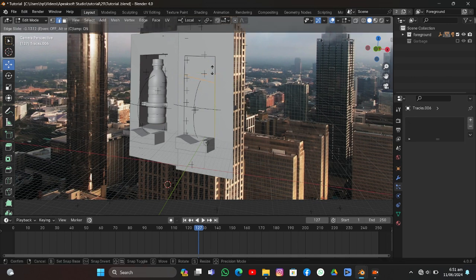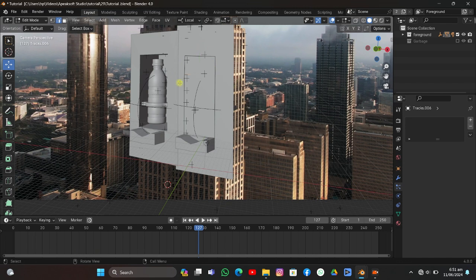I might not explain every single thing because I really don't remember what I left. I'm gonna hit K and I'm gonna make these loop cuts. I'm gonna hit Control B to add enough loop cuts by scrolling up like that. And we don't have so many right here, so I'm gonna hit K again and add it here. When it's reached the destination, hit Enter to confirm it. And again, I'm gonna select this one also, and hit Control B to bevel it like that, so we have enough faces to work with.